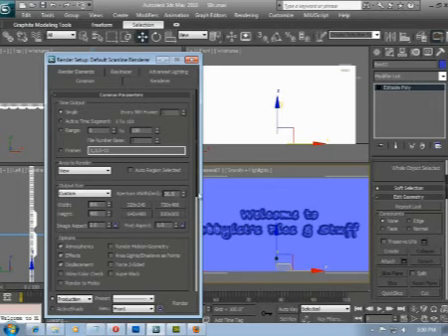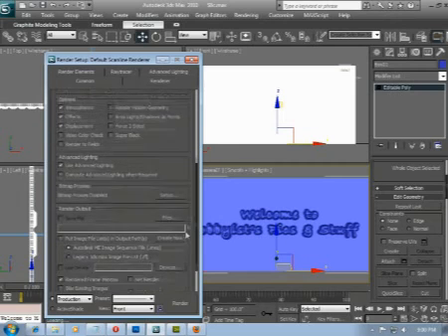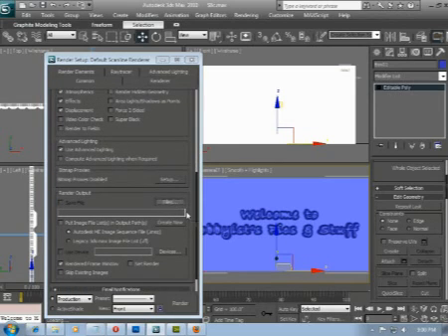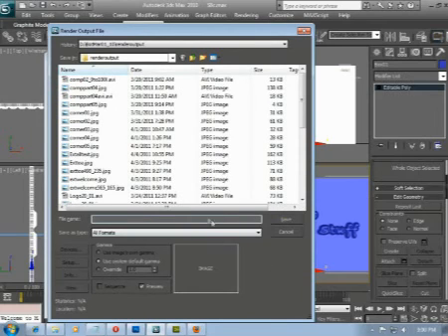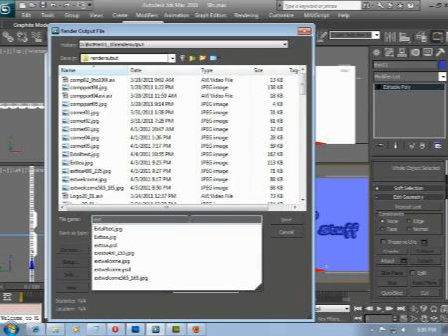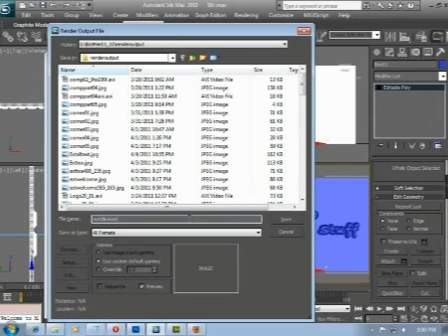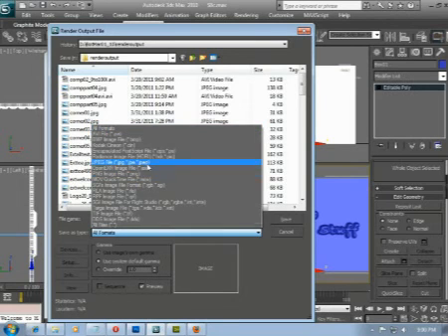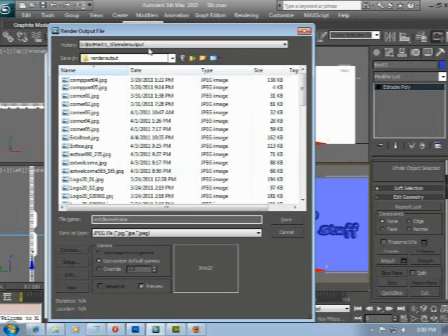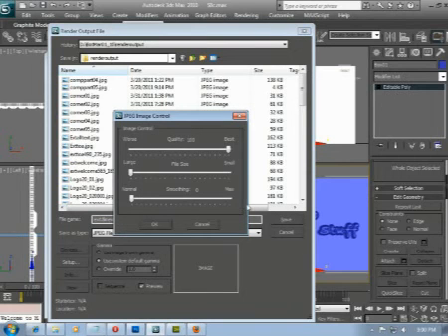If we grab the slider and drag down to get to the render output settings, we first need to click on the Files button and then enter the name for the JPEG file we're going to create. I like EXT for extruded, and this is the 2-line version, and it's the welcome text. And JPEG from the drop-down should be perfect. The default output location for our JPEG is going to be the render output subdirectory under the current project. So as long as we know where to find it, that should be fine.